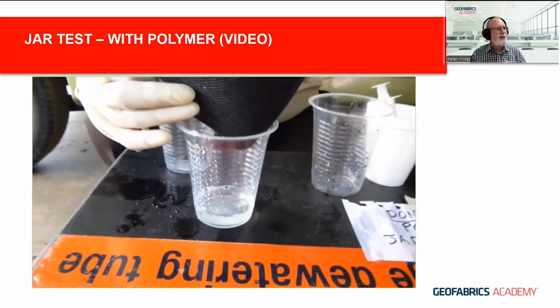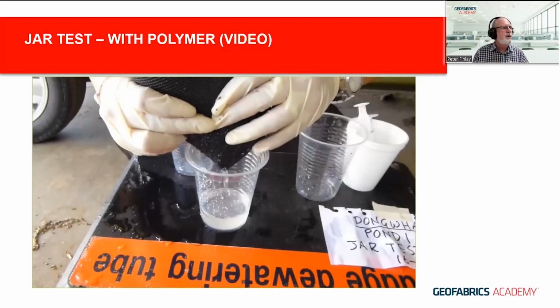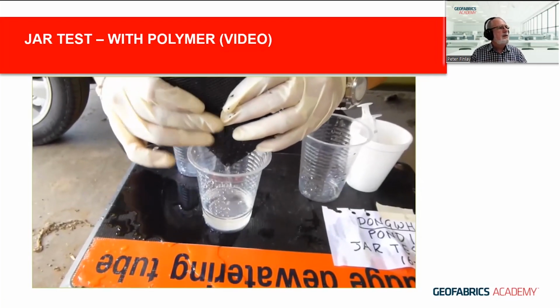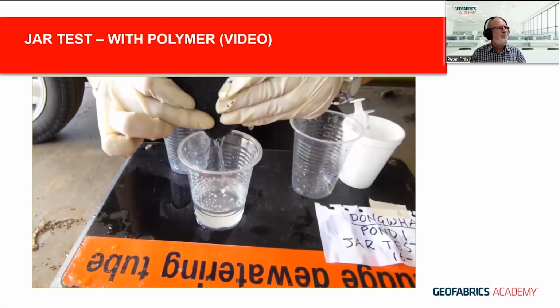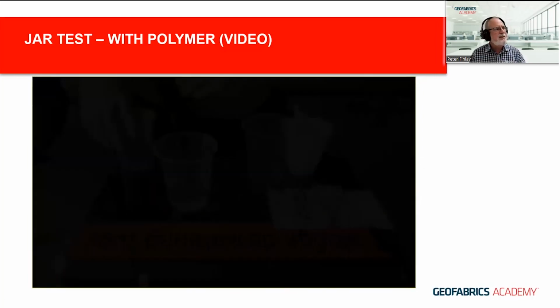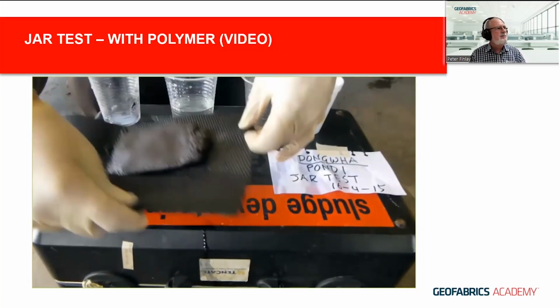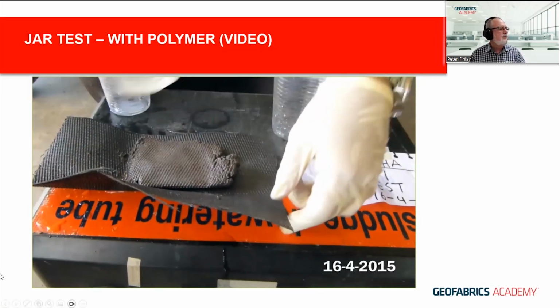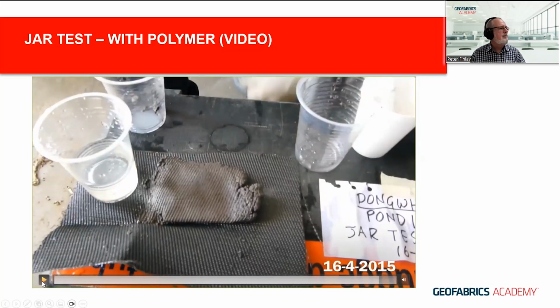So we typically leave that several minutes and allow it to dewater naturally. Here he's giving it a bit of a help along. And as you can see, even with some bit of force there, it's not breaking that apart and getting a lot of sediment through there. So that's what we'd see as a good result in the test.